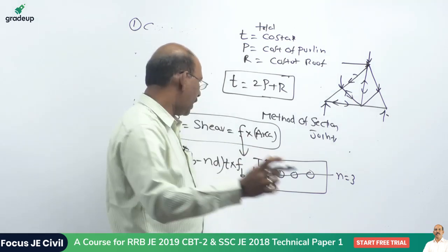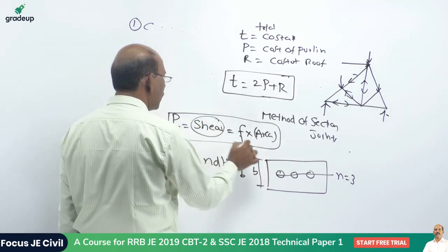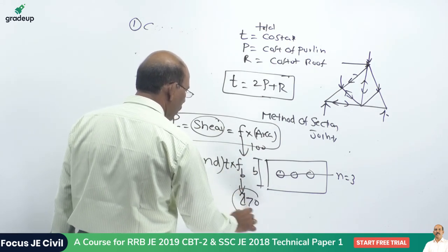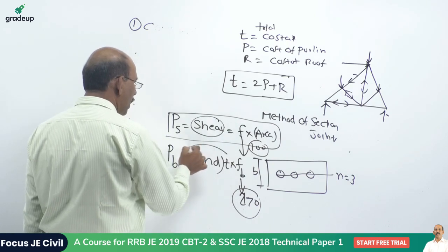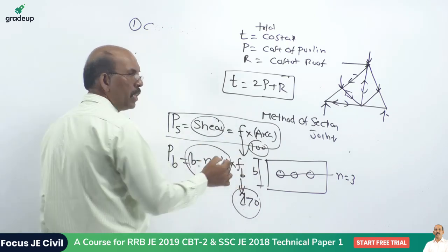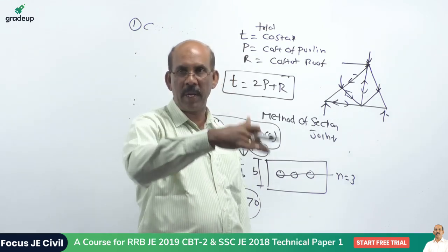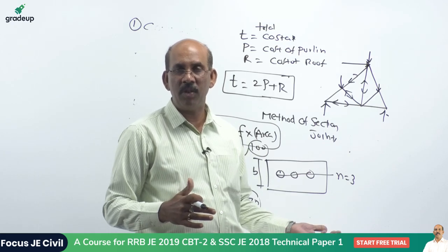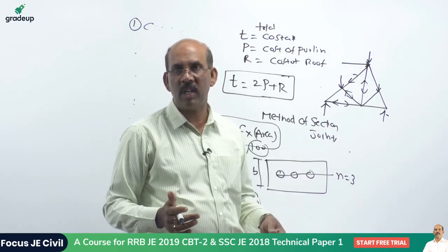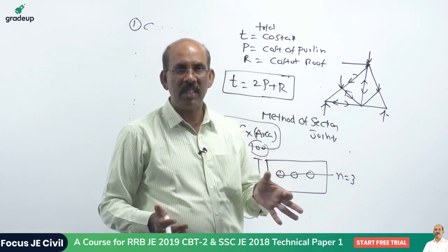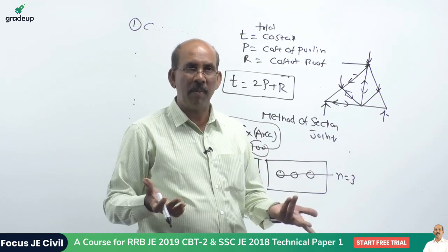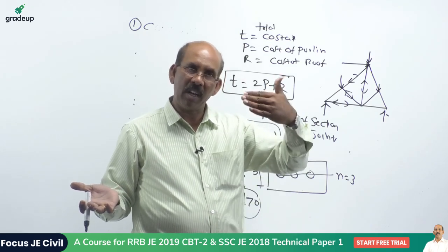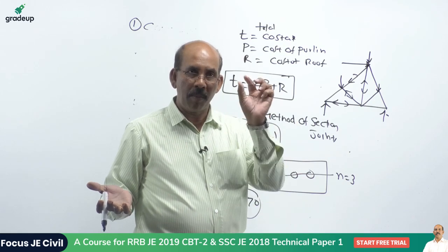So this is the stress in the bearing and shear. With reference to shear it is 100, and with reference to bearing it is around 270. Normally this bearing value is higher when compared to the shear. The FB value is 270, whereas the shear is only 100. That is the reason this is the minimum strength of the bolt, and you have to always consider the minimum value in the design when you are calculating the number of bolts.